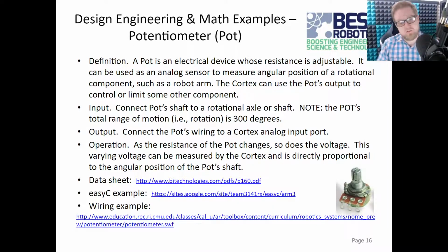Well, a potentiometer is a very effective way to do this, and it will be connected to the analog outputs on your cortex. So there's a lot of different materials and ways you can wire one of these up, and they are in the consumable kit. So you are able to solder to these leads for a pretty permanent connection if you so wish. And you can see there's a couple of different links here on the presentation. Mentioning again that you have a digital version of this, so you can't access the links here in the video, but you can if you go into the presentation and open them. And they'll show you how to wire it up and how to attach them.